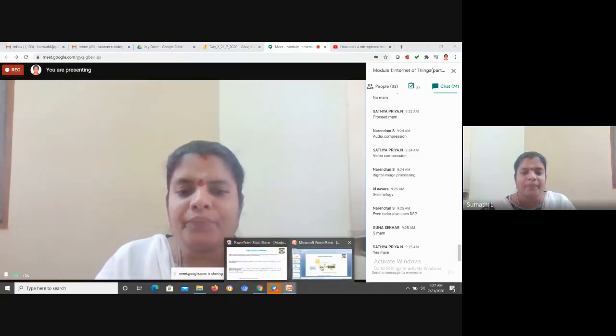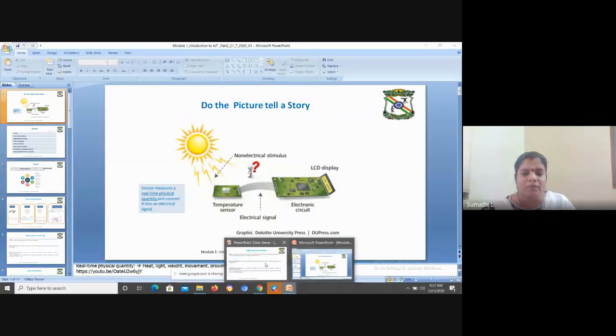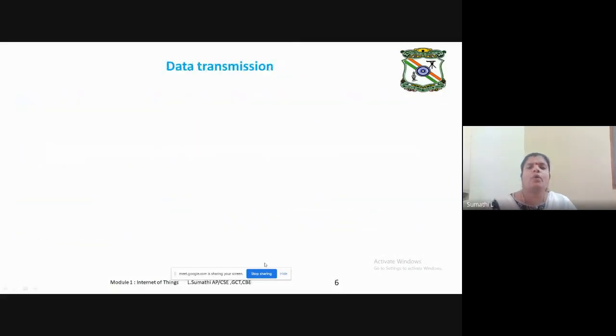Okay, getting back. What is data transmission? Right now, I have sensed from the sensor, transformed to electrical energy. Then, as the electrical energy is weak and has noise, I removed the noise, amplified the signal, and then converted the signal into digital. And then I have applied this digital signal into DSP and processed it. Now I have to transmit.